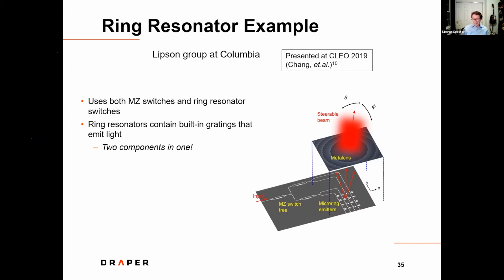They work on a single wavelength, and that wavelength is very fabrication dependent. So typically you have to have lookup tables and know the right wavelength that each one's going to operate at, or tune it. And then also, if the temperature changes, they can change too.